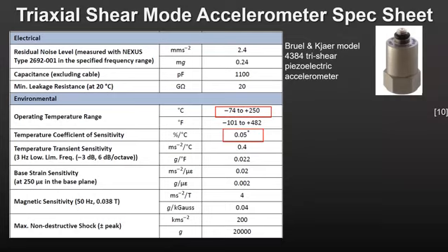The sensor can withstand a shock of 20,000 Gs, which is an enormous number. Even with the miniaturization of accelerometers and their integration into electronic systems, piezoelectric accelerometers are still sold in high quantities. The capacitive and piezoresistive accelerometers cannot handle such high temperatures or levels of shock and acceleration without permanent damage.